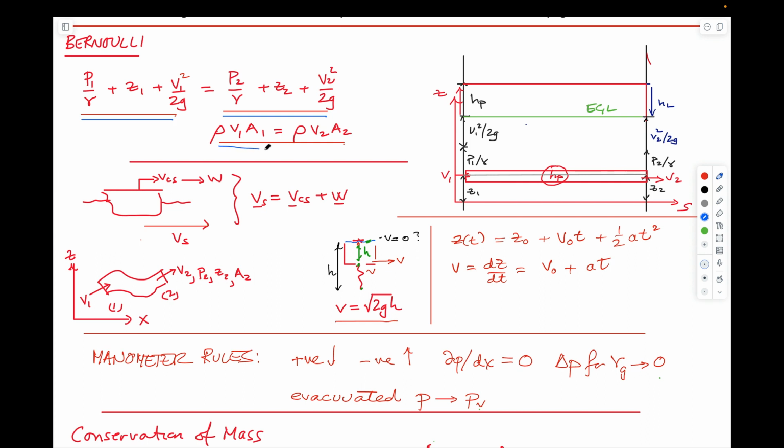If you only have 4 knowns, then you have to constrain it somehow, and usually you constrain it by writing a simple conservation of mass within the stream tube, where you can write mass rate in equals mass rate out and link the magnitudes of the velocities to each other through those geometric cross-sectional areas, and therefore constrain these to be just a single parameter instead of 2 parameters.